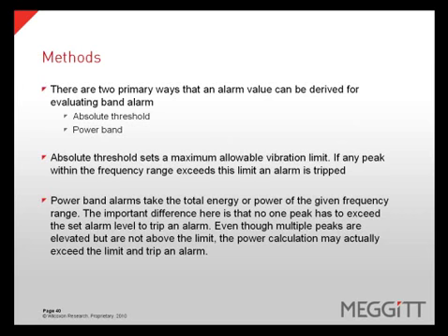Absolute threshold, which sets a maximum allowable vibration limit, and if any one peak within the frequency range exceeds this threshold, an alarm is triggered. The other method is using a power band.